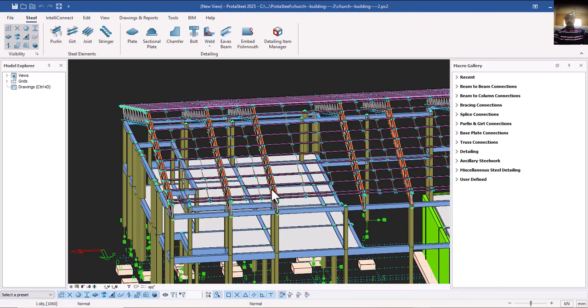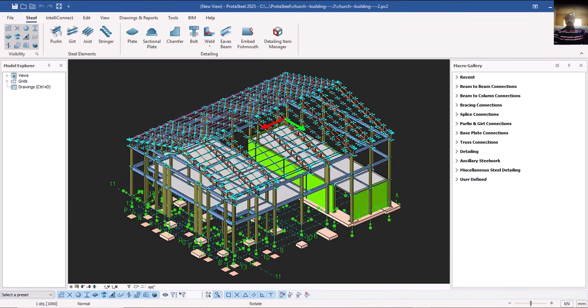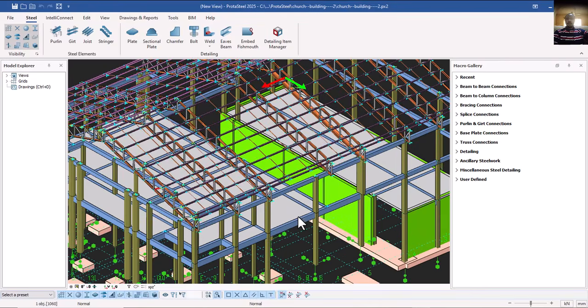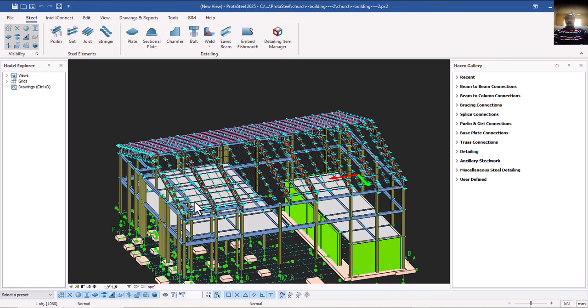And along the line, we discover that maybe the majority of them are failing, which we have done last time, and the ones that are now passing are, for example, 90 by 90 by 13. Now what you need to do is detail all of them as 90 by 90 by 13 to save yourself stress, which automatically makes every other one pass even more than expected, isn't it?